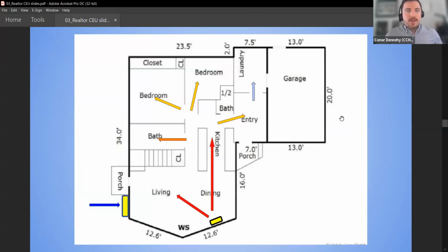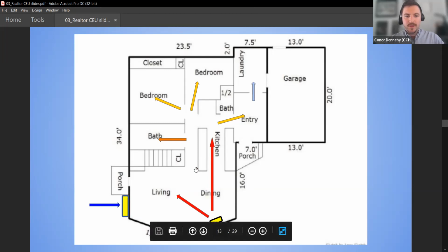A lot of people, even before we get into the specific science of is this appropriate for your house, can think about just the layout of your house. The more open floor plan a house, the more applicable a ductless heat pump is for it. You can see we've got these yellow boxes here, which simulate the outside unit of the heat pump.